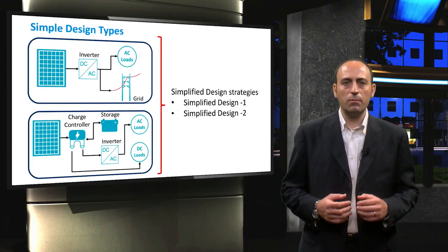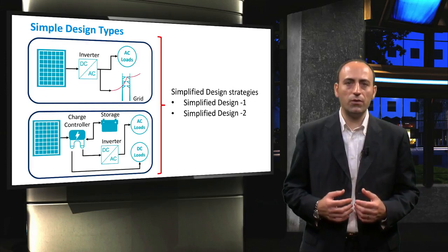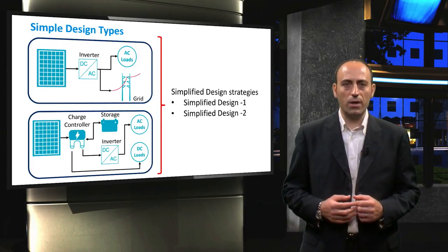The second strategy is a bit closer to reality since it includes additional details such as charge controller type, inverter type, and maximum power point tracker. For both these simplified strategies, many oversimplifications are applied. These include the use of a simplified load profile and disregarding the location's meteorological effects like ambient temperatures and the wind speed. Moreover, for the simplified design, we simply use the standard test condition data of the PV modules, and therefore we do not take into account the sun position or PV module orientation.